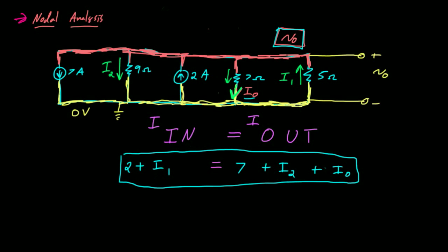We've described this circuit fully in terms of current in equals current out, and we've only needed to do that for one node. Generally, when we do these circuits, we will need to do that for one less than the number of nodes that we have, or every single node except for the ground node. So anyway, that's the important stuff from the last video.